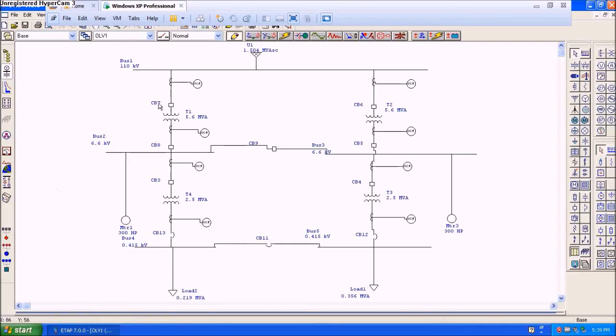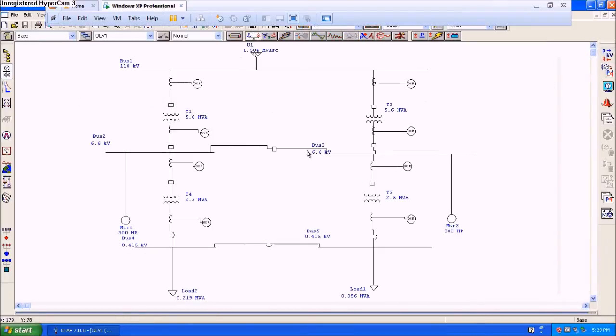The feeder actually automatically takes these values. We don't have to insert over here. We have to first configure the bus. In the bus we are taking IEC settings and we are taking typical data, and other things are automatic. We don't have to put much. So we can take from the library. Initially we have to just put 110 kV over here, and the name is bus 1.